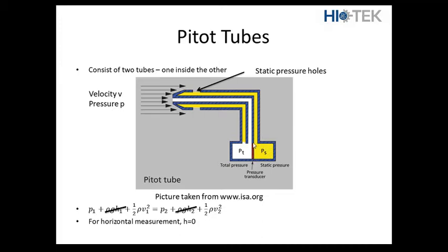And what you normally have here is a pressure transducer, which is some kind of electromechanical piezoelectric material that will deflect based on the variations in this pressure and give an electrical signal which the pilot will then read via his dials. So if we use the equation we had before, we're assuming the plane is not changing altitude. That's a different meter that we're looking at there. It's an altimeter. We're not talking about that here.